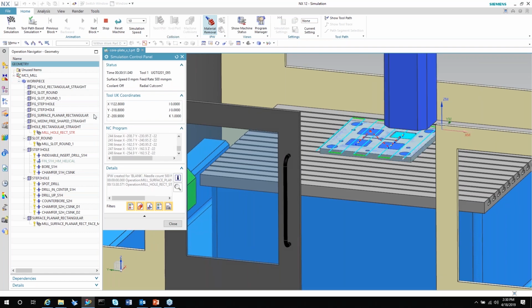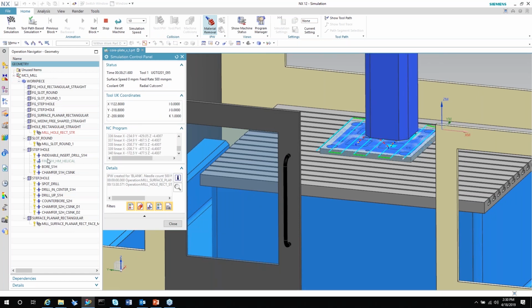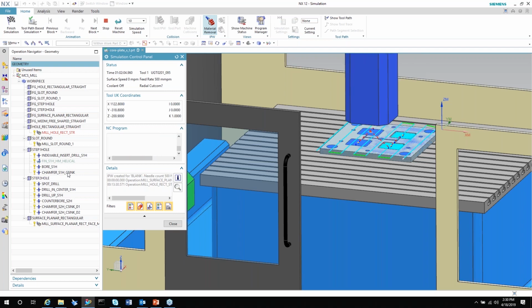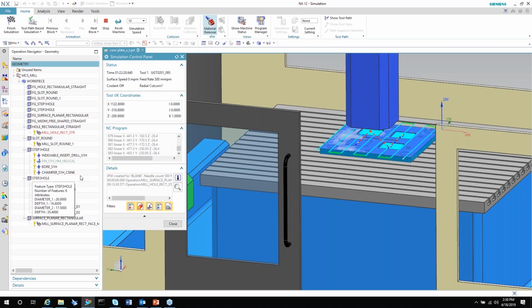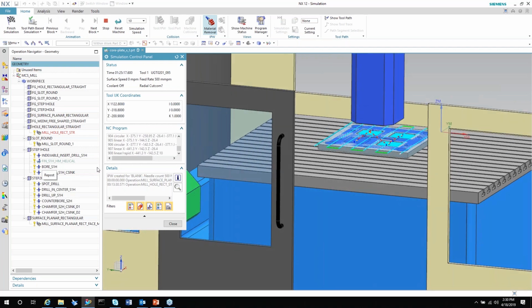And then, regarding how they said that you can skip around and do any type of operation: you can skip around and do any operation only in toolpath simulation. If you do G-code simulation, because it has to produce the IPW for an operation that's further down the line, it won't allow you to just pick any operation and run. What it'll do is make you create an additional program folder to put that operation in, so that it's running from a program folder, because some machine tool simulation kits must have a program folder to have some UDEs listed in it.